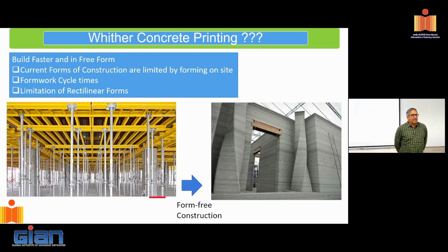So at some spans, around 10 to 12 meters, you'll realize that it's almost impossible to design a single RC beam, because the minute you start making the beam deeper or bigger, you add more weight, and to provide for that additional demand, you actually have to make the beam deeper. So basically that is the downward spiral we are talking about in RC design. And oftentimes we find that depending on the loading and the end conditions, the boundary conditions, the break-even point would be about 10 to 12 meters, beyond which doing a single RC just doesn't make any sense. You just cannot.